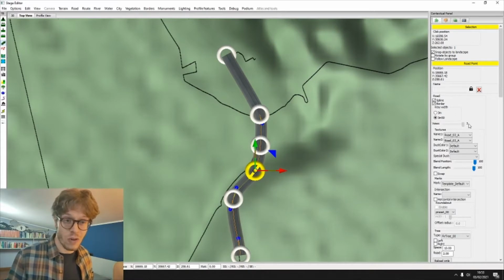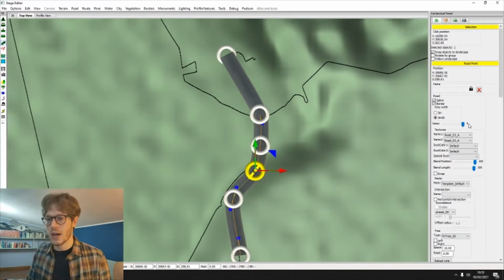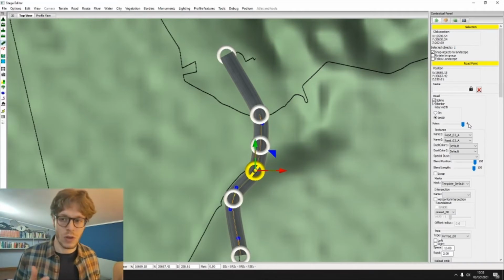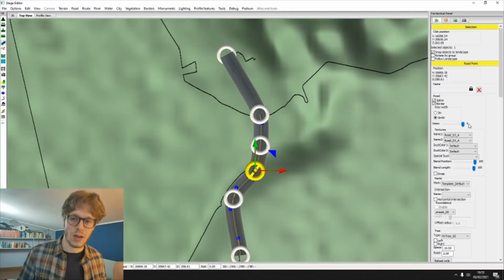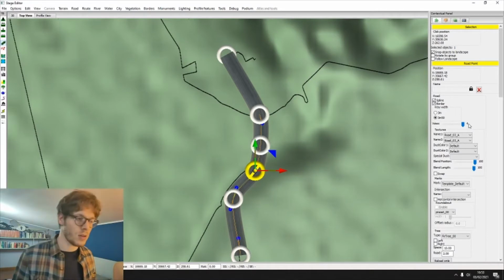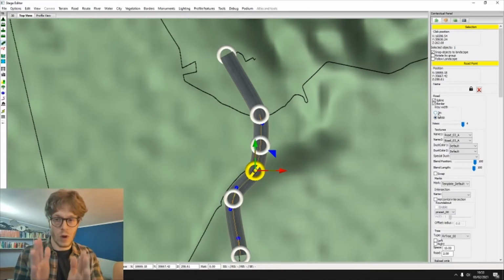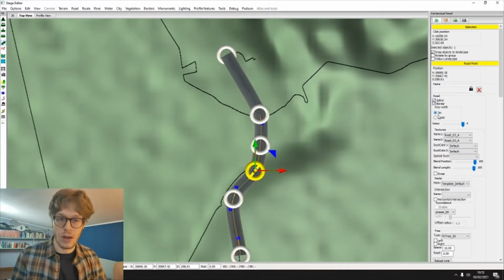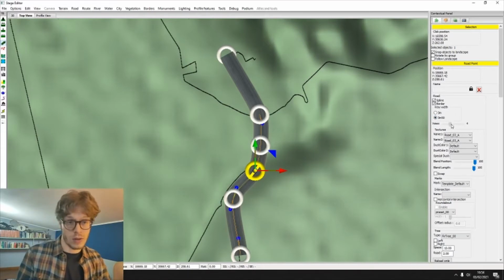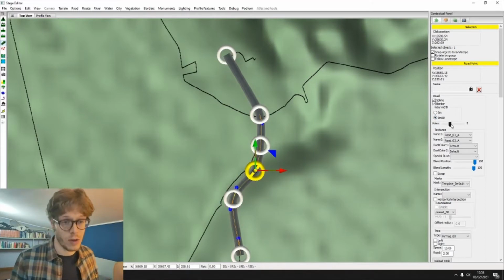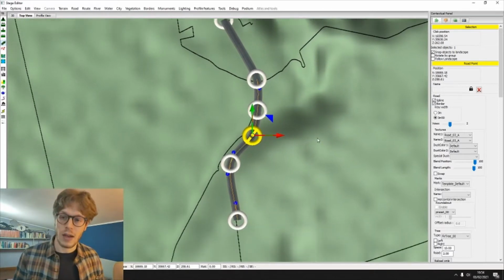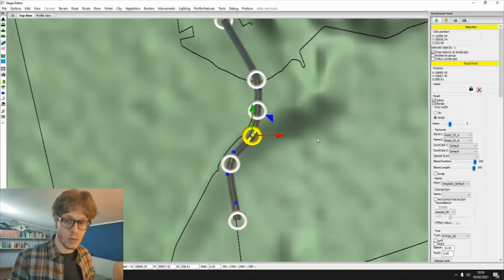And then there is 4 that is different because it's more like a highway, the one that you usually take when you go on holiday, when you move from one country to another and you pay the ticket and you use this. And then also I remind you, you have different sizes of one-way. It is 3 meter and 3 meter and 50. I suggest you to keep two-way 3 meter and 50. But then if there are some points we can make it narrower or wider.